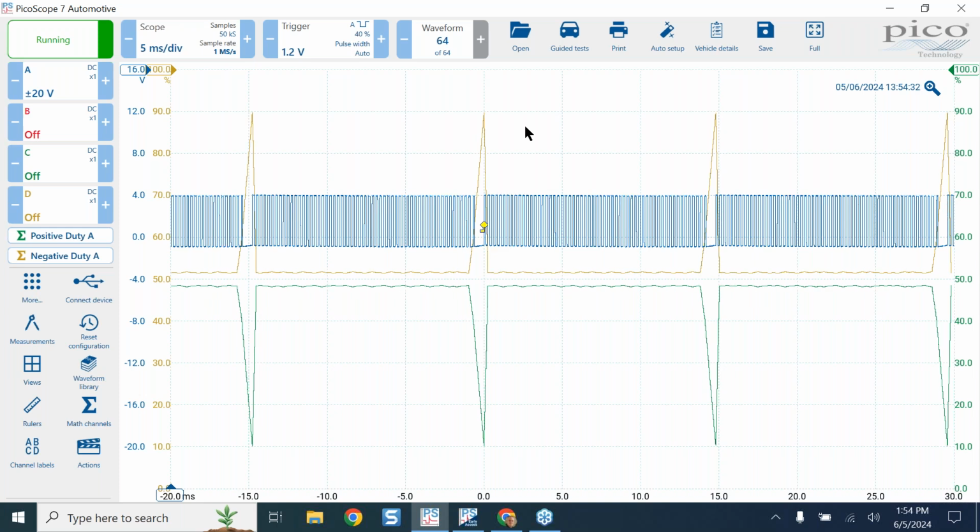You're certainly not going to catch it by looking at it that's not triggered. So if I would turn the trigger off, and you know that is in free run mode at 5 milliseconds per division or 50 milliseconds per screen, what's the chance, even on a buffer, I've got 64 waveforms in my buffer, what's the chance of you catching that glitch? I don't think it's very good. You can do advanced triggers and maybe set inside and outside ranges for pulse width. Maybe that'll work.